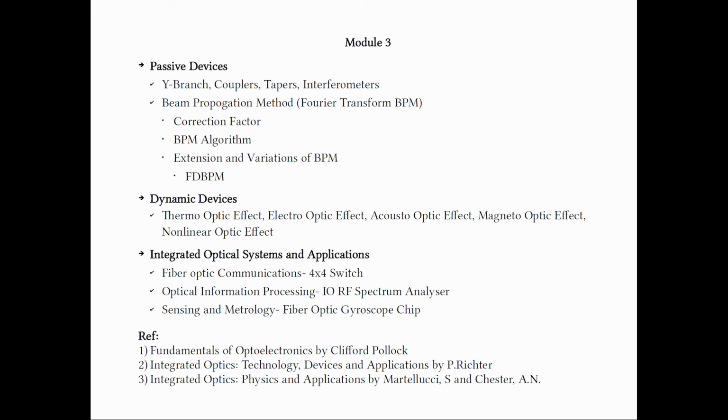acoustooptic effect in the form of a spectrum analyzer. A typical spectrum analyzer will consist of an acoustooptic cell or the IDT pattern, which will create a grating on the chip, and we have noted that integrated optical lenses are used for focusing and defocusing, where the functioning can be analogous to that of bulk lenses. We have not considered the integrated optical lenses in this particular course, and from the references given at the end, you can look at the properties and see what the differences are between the lenses in